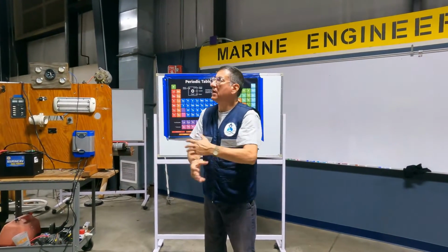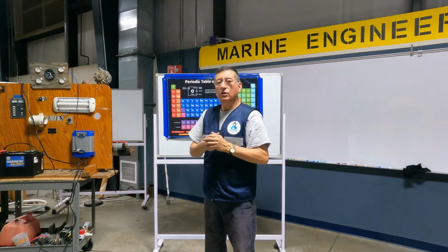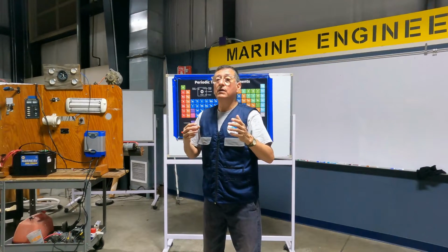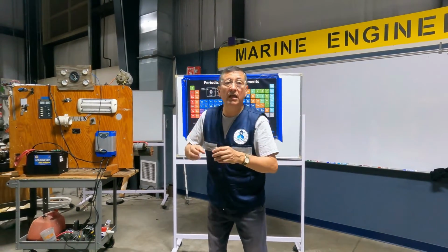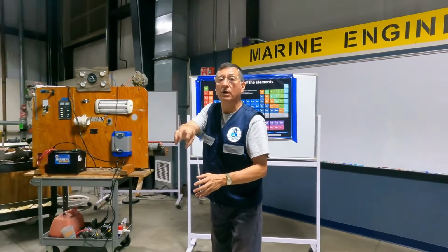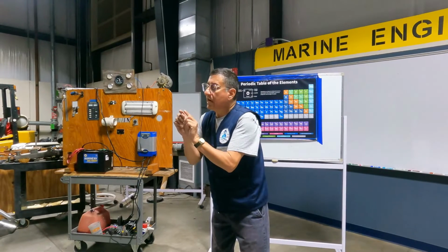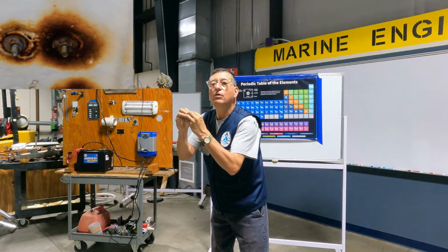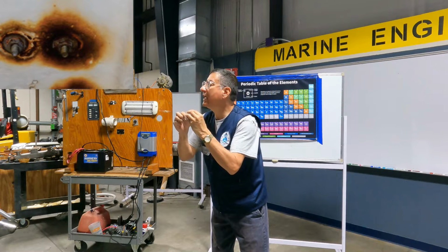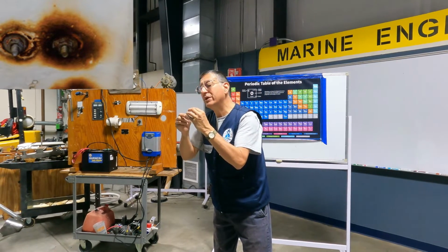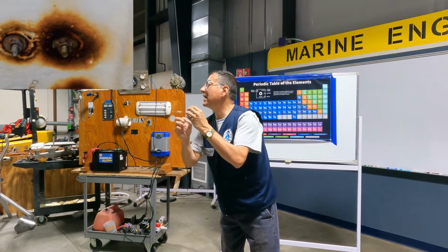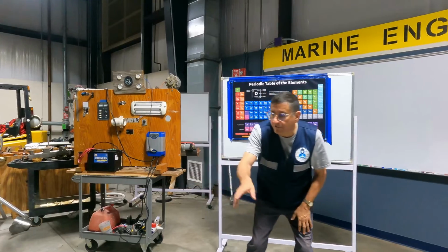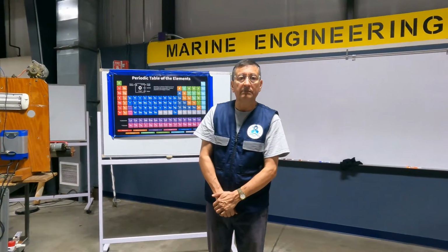How many dissimilar metals are over there? 3 or 4, no? What happens when you have 2 dissimilar metals in a marine environment? The more noble attacks the less noble. The less noble releases the electrons, and the more noble attracts them. What happens in that boundary, in that area around the more noble with the less noble? That area will be eroded. What happens in 2 months with that area? It's attacked with pitting corrosion and is perforated. And wow, the bottom of my refrigerator is completely eroded in 3 months.